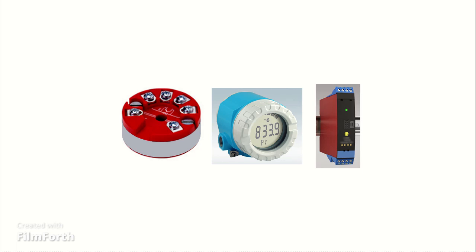These types of instruments measure the resistance of the RTD and then convert that resistance to its equivalent temperature, and then convert that temperature to an electronic signal that can be transmitted to another instrument or piece of equipment up to a kilometer away, depending on the type of transmitter.